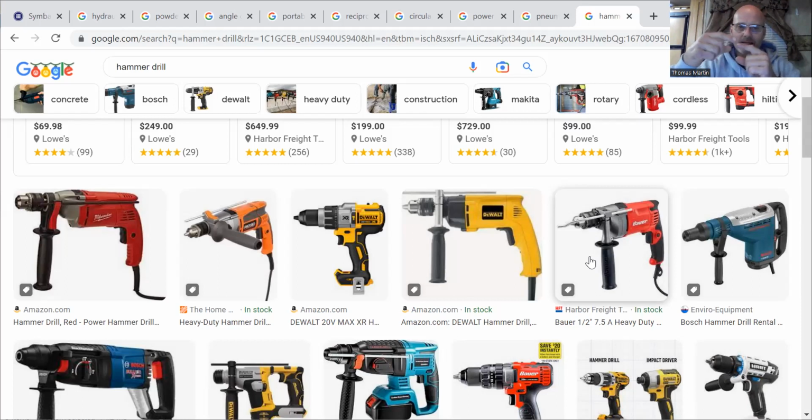The sand that's a part of that concrete will actually crystallize and cause that metal to burn, get so hot that it'll actually melt that bit. So it's super important if you're drilling through masonry, you're using a hammer drill with the appropriate type of masonry bit. And if you'll look on page 11, it gives you some examples.